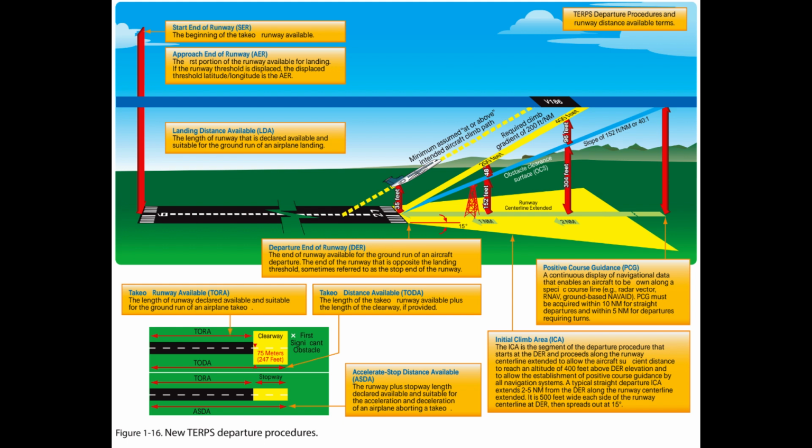Standard formula: CG = (O - E) / 0.76D. DOD option (asterisk): CG = 48D + (O - E) / D. O equals obstacle mean sea level (MSL) elevation. E equals climb gradient starting MSL elevation. D equals distance, in NM, from the DER to the obstacle.